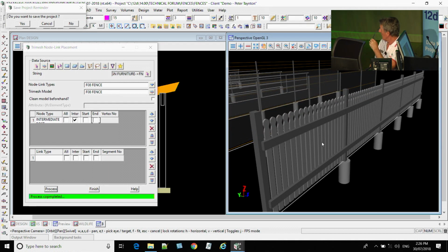Okay, so that one there, I picked the shape, which I just drew, the paling, and then I went through the same process I did before. I did a post, footing, a rail, I picked the shape, and there's an option in there to rotate the paling if it's not the right way. So you can make it 45 degrees, 90 degrees, and it will then do the paling like that for you. And again, if it's got a spacing involved, it will work out where these are supposed to sit for you every time. You won't have to worry about that.